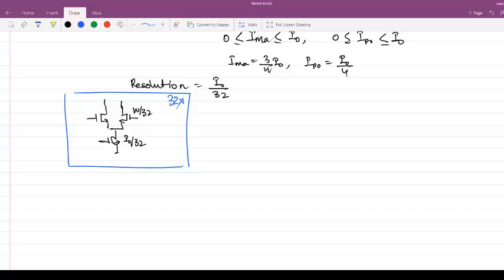So the thing is, if you consider everything ideal, this will not change anything. But when you start considering the capacitance at different nodes within the circuit, which are switching with different potentials, they will introduce a data dependency at the output. So if you want uniformity, whether you use one cell or two cells, you use it in a way that everything is uniformly segmented.